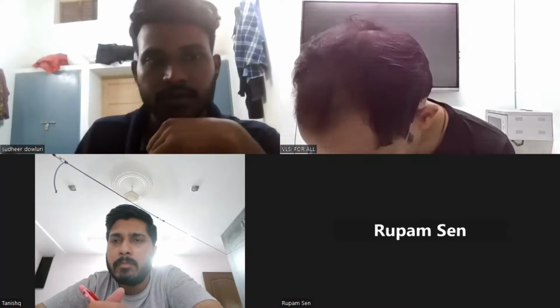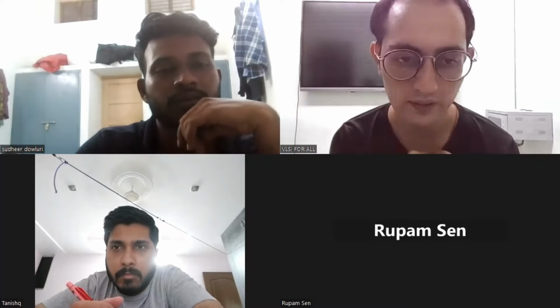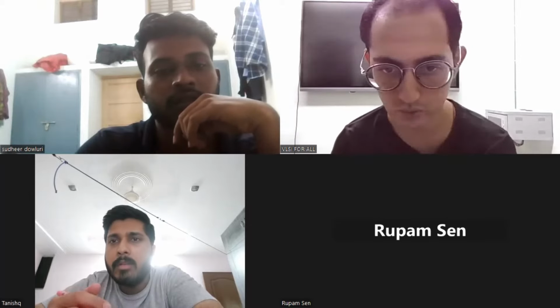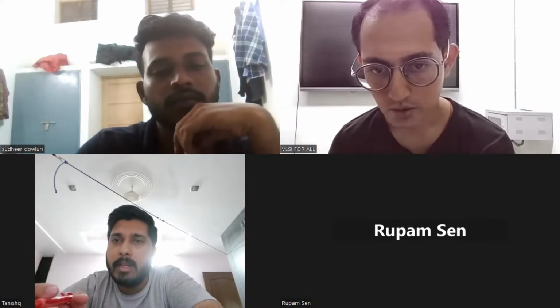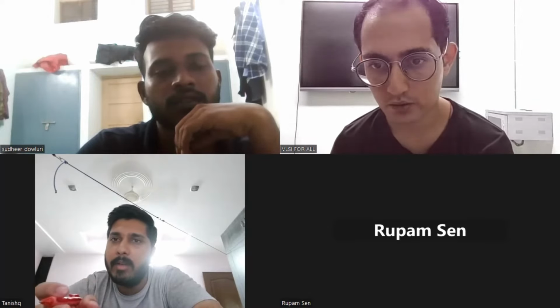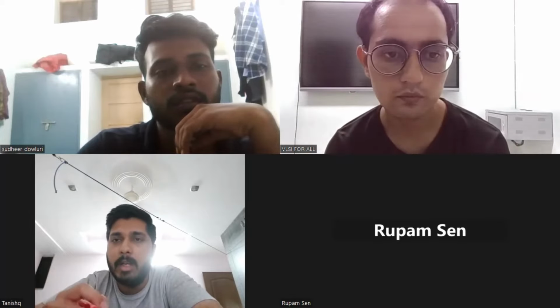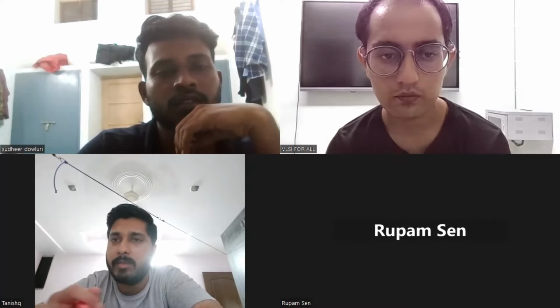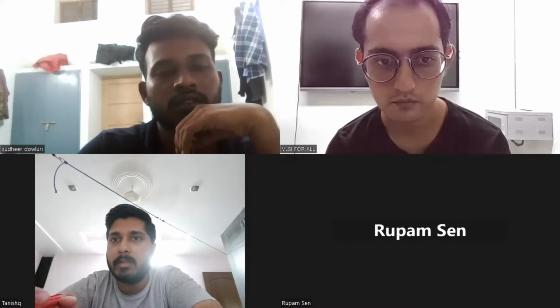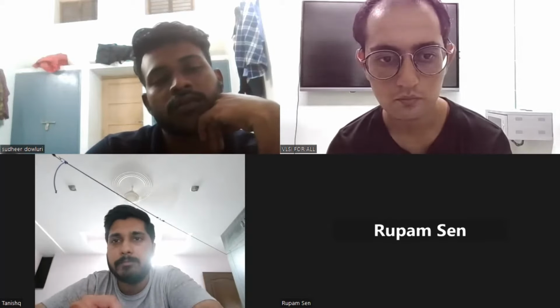Okay. My next question is, what is the difference between blocking and non-blocking assignment statements? Sir, in a blocking assignment, when we assign something, it is first evaluated and then it proceeds further to execute the next statements. But in the case of non-blocking, it does not block the flow of the program, and it proceeds further as soon as the first statement is processed, moving on to the next line of code.